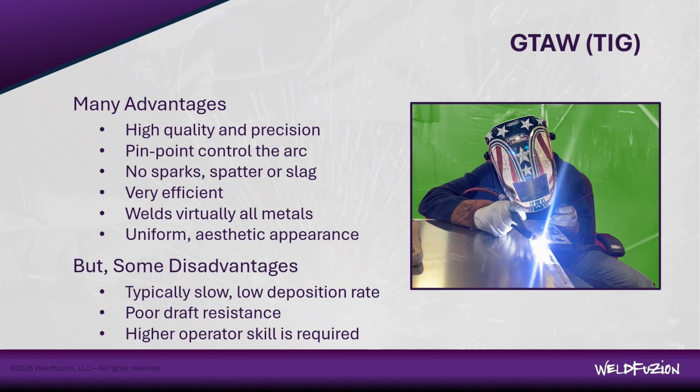In the past, TIG has also been quite expensive. So we can't TIG weld everything. And TIG welding is selected primarily on one factor, and that's weld quality. When the application cannot compromise quality, TIG's the choice from an arc welding perspective.